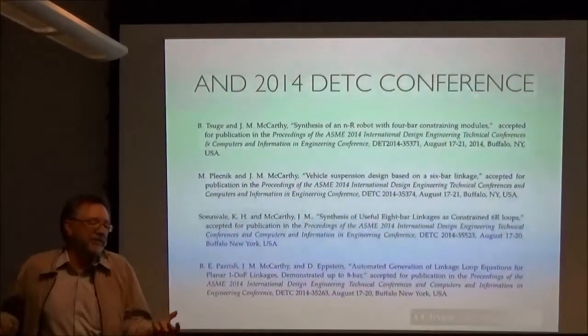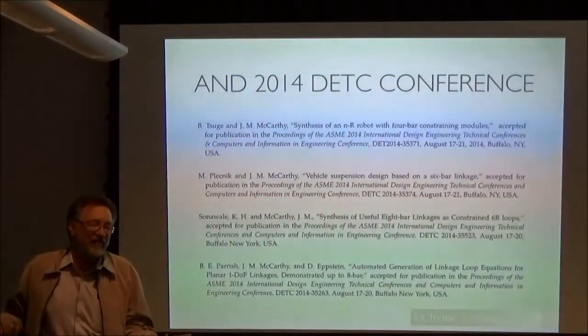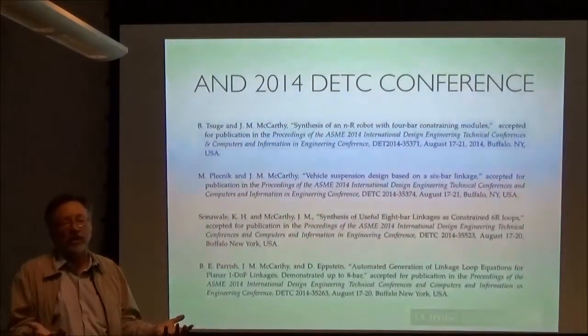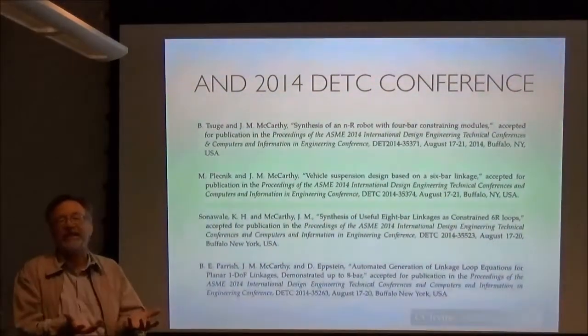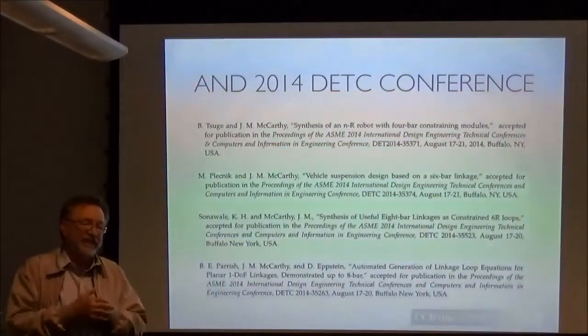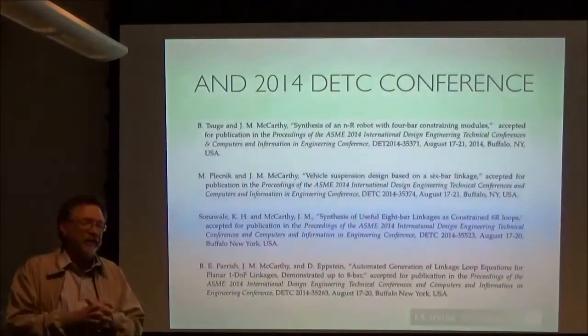Because the main problem is you can't do the synthesis by itself. Your synthesis routines give you linkages that don't work. So once you've done the synthesis, you immediately have to do the analysis in order to verify that they work.